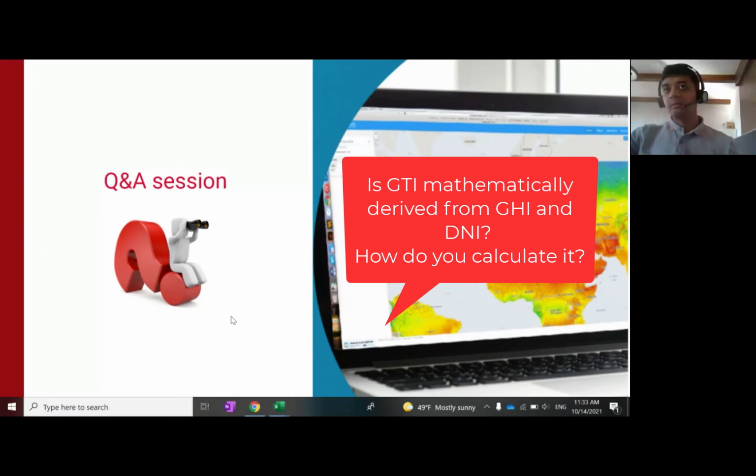Yeah, and I would just add that we are using the Perez transposition model, which is used in PVsyst. However, there might be some differences in the exact implementation of the model, like the coefficients used and so on. So it may be possible that when you put Solargis GHI and diffuse data into PVsyst, and you calculate the GTI in PVsyst, you might get a result that is, let's say, 0.5 to 1% different compared to the result that you get from Solargis.